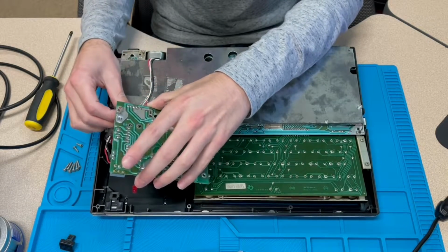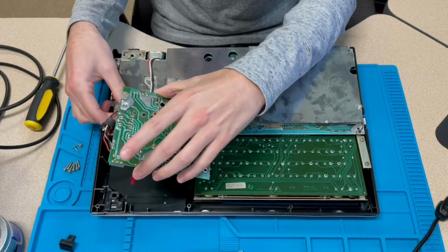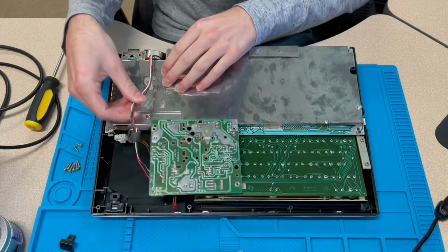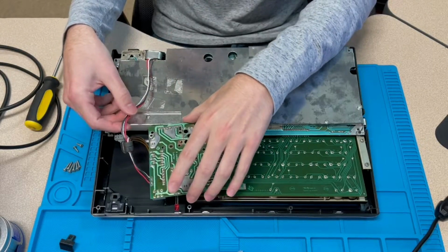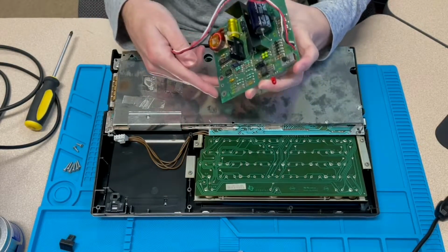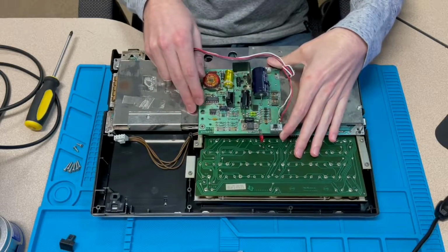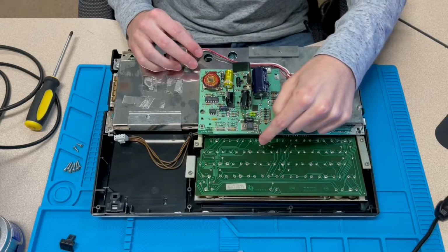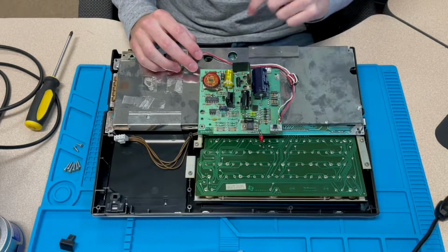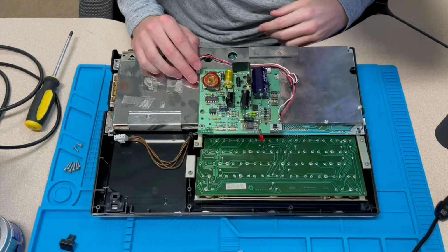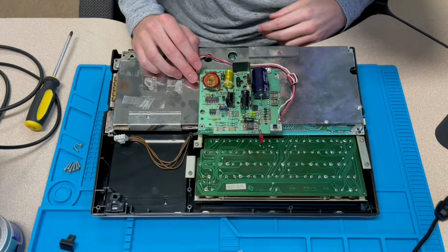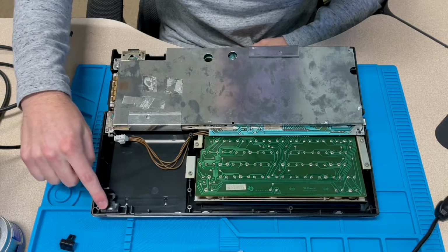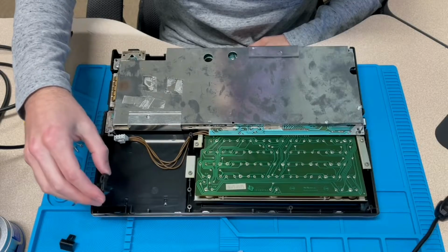Move this connector here. And then remove the tape that I have holding this down. And that works too, ripping the tape. So there's the power supply board for this TI computer model. This one's actually got a LED on it, letting you know the computer is on. It's got a massive capacitor right there. 3,300 microfarad at 35 volts. And this little plastic thing right here is part of the power switch mechanism. It slides back and forth. This just lifts right out.